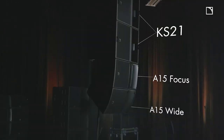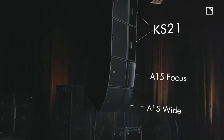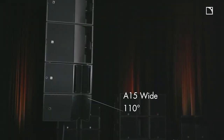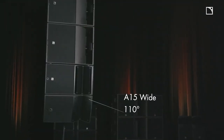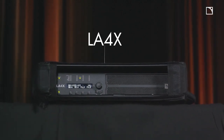I'm set up here today at our office in California with the new medium throw line source array, the A series. The array behind me starts with two KS21 and an A15 focus with an A15 wide. The A15 focus has its pan flex set to 70 degrees, and the A15 wide has its pan flex set to 110 degrees in the horizontal. To power this entire setup requires only one LA4X amplified controller.